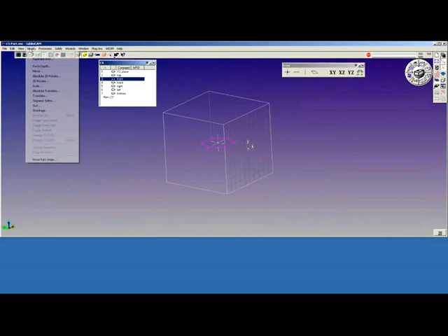Change CS XYZ, which we've used previously, associates geometry to the active CS without moving the geometry. It stays in its same location, but associates with the active coordinate system. The other choice, change CS HVD, will physically take the selected geometry and move it into a coordinate system.